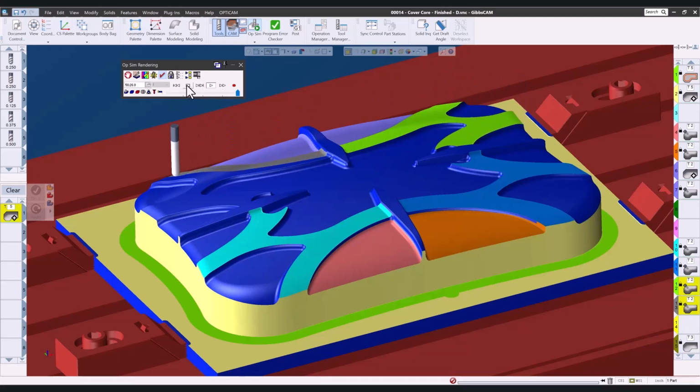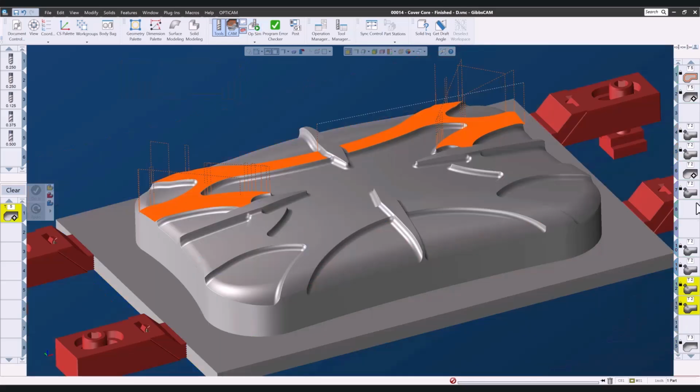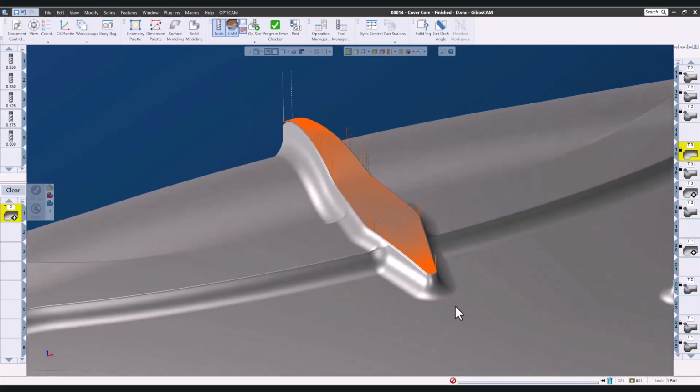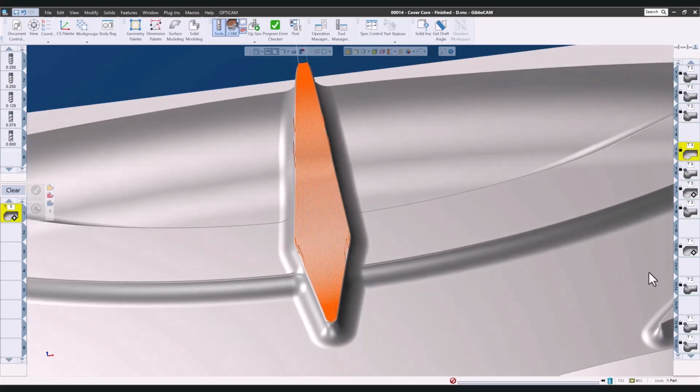And with either, by setting appropriate cutting tolerances and stepovers, fitting arcs where appropriate, you can easily achieve the surface finishes your customers are looking for or produce a part that requires minimal polishing if that's the finish that you need. Moving on, for the 4 diamond-shaped bosses, I used a 2-curve flow from the multi-surface process for this one.